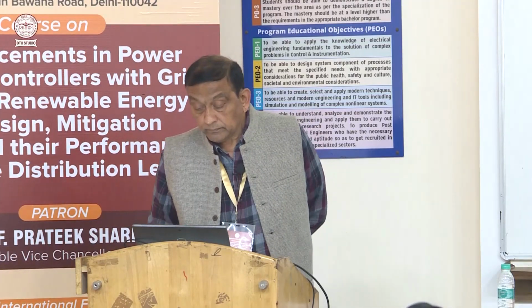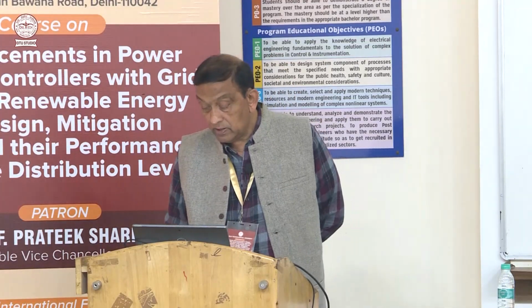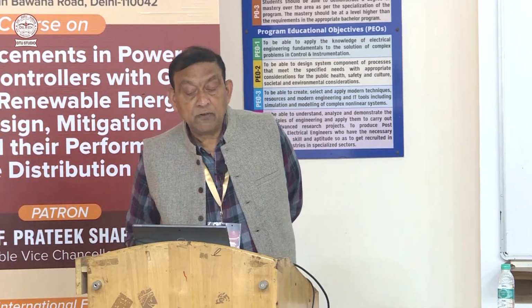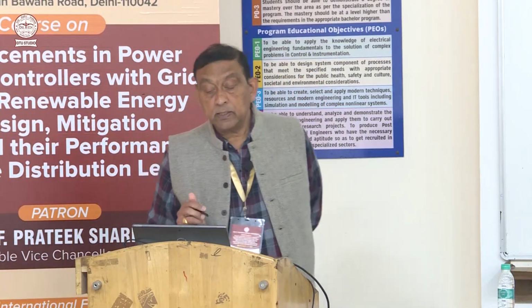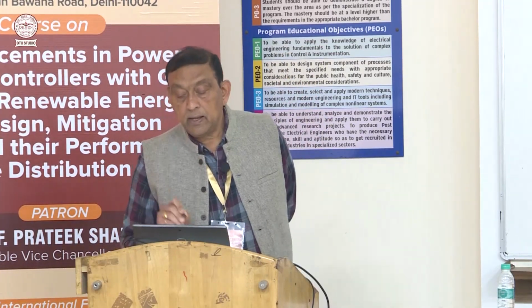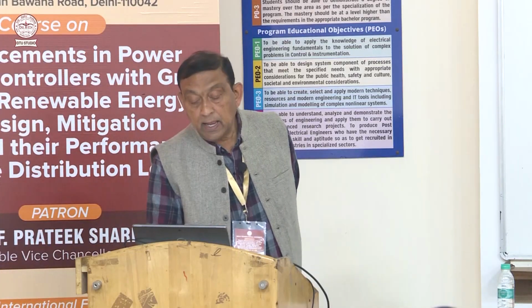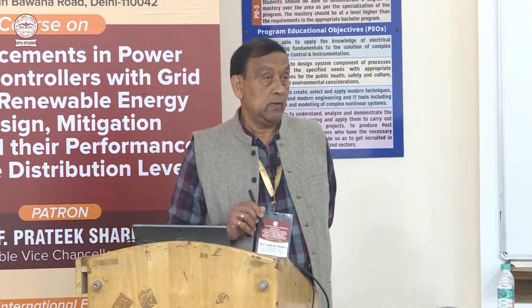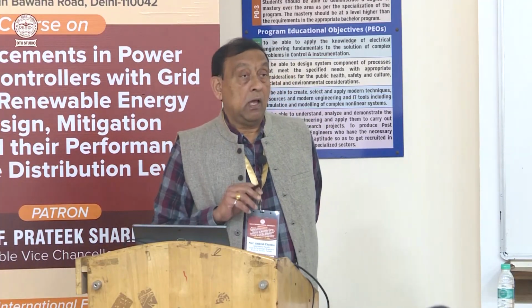So now coming to the PMSG based wind energy conversion system. What are the features of a permanent magnet synchronous generator based direct driven wind energy conversion system? One important thing is the elimination of the gearbox, because the gearbox is always a problem.